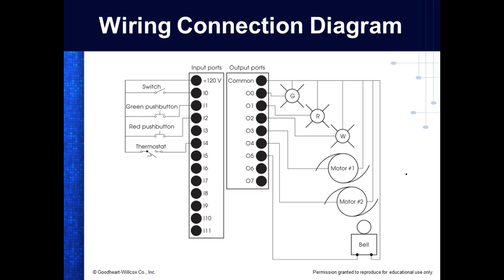So this is what they're showing. Here they're saying common, but what you have to understand is sometimes the common is selectable. Right? Does that make sense? And on DC now, AC technically does not have a polarity. So this plus and minus and this sinking and sourcing only comes into play if you have DC input and DC output modules. And DC input is very, very popular, and 24 volts is very, very popular.